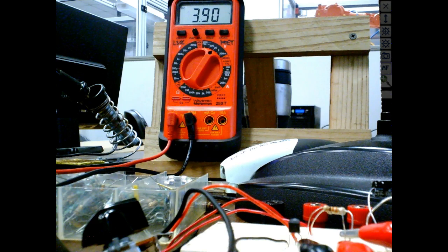We saw that with a regular diode, right? We hooked it up over there, we reverse biased it, and I heated the diode up. The leakage current went up. Well, if your collector current goes up and we don't change our base current, then that means the beta has to be going up. And this is why beta is in such a big range.